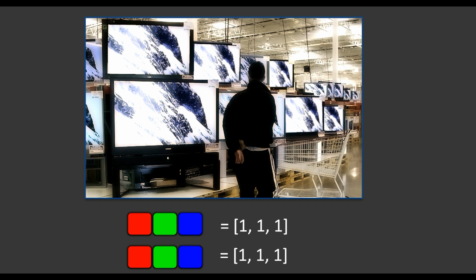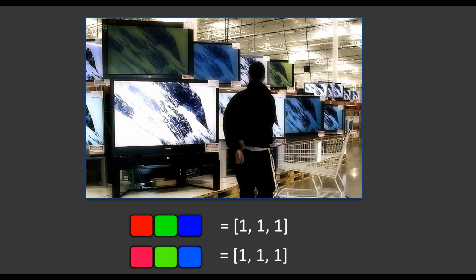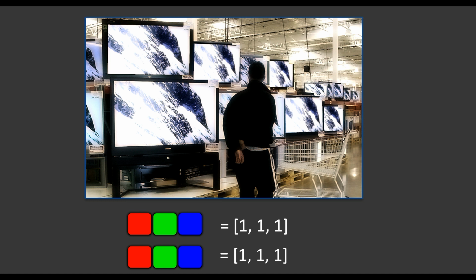So the goal of sRGB is to provide standardization or a common denominator for all these different devices. When working in sRGB mode, all displays, regardless of type or manufacturer, should display any given RGB triplet in the same way, or as the same physical color. For some displays, this can even mean narrowing down their color gamut just to comply with the standard.